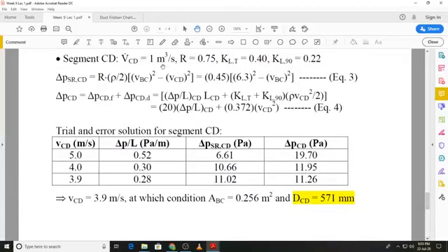You can see that this time the volume flow rate is further reduced, because another 1 cubic meter per second went into another diffuser through another T, and so we have a volume flow rate of 1 cubic meter per second. Then we had two sources of minor losses, that is again the T through, and a 90-degree bend. The static regain factor remains unchanged, it is 0.75.